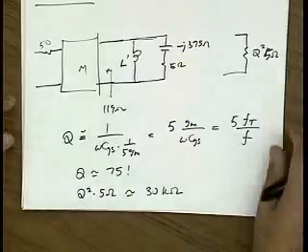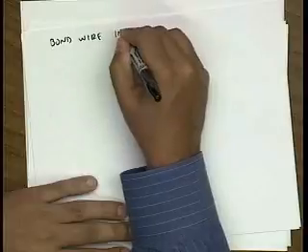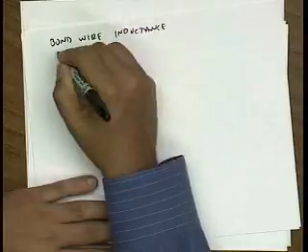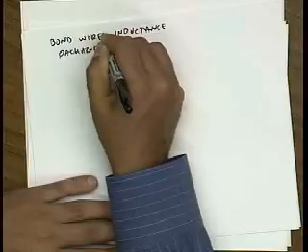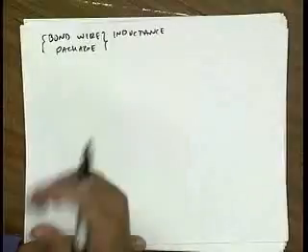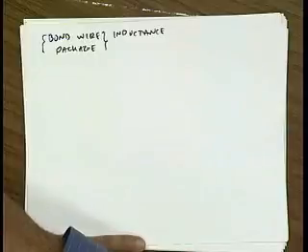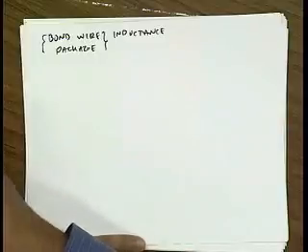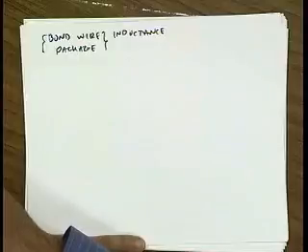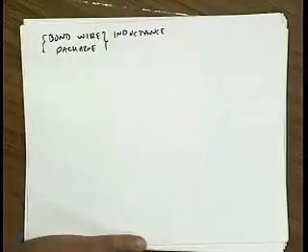All right. Well, last lecture, you guys remember that we talked about bond wire inductance, I should say bond wire and package inductance. If you ever build an LNA, even if it's on chip, it has to interface with the external world. Usually your antennas are not on chip. Say at a gigahertz, the wavelength's 10 centimeters, so even quarter wavelength is 2.5 centimeters, right? So at a gigahertz, you can't put an antenna on chip. It's just physically too large. So the antenna's got to be on the board or some external place.